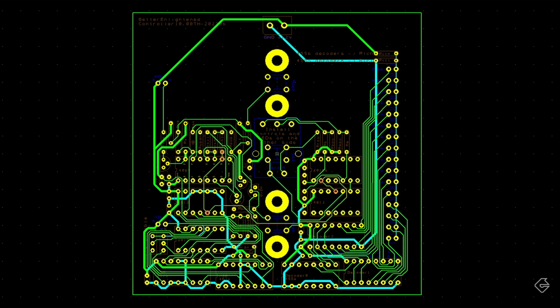And there it is. You can see if I'm highlighting the clock net, once I put that trace in to connect those, they are now actually part of the same net. Here's the reset nets, and you can clearly see there are two separate reset nets. Now you can see that they're connected as one net. The next disconnected net, I believe, was the press net. And if I highlight it, sure enough, you see they're disconnected. Let's connect those with a trace. That was a winding trace that we had to put in, but they're successfully connected now.